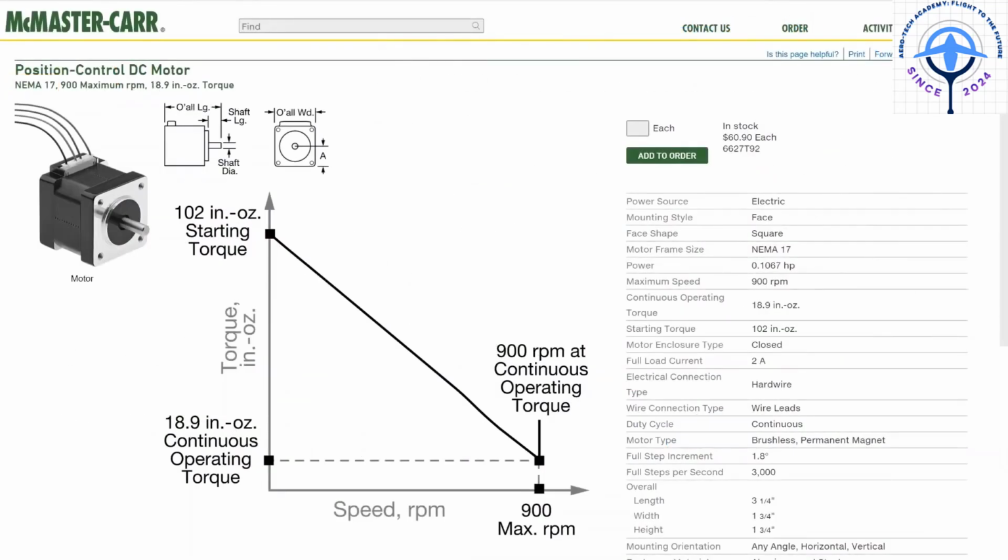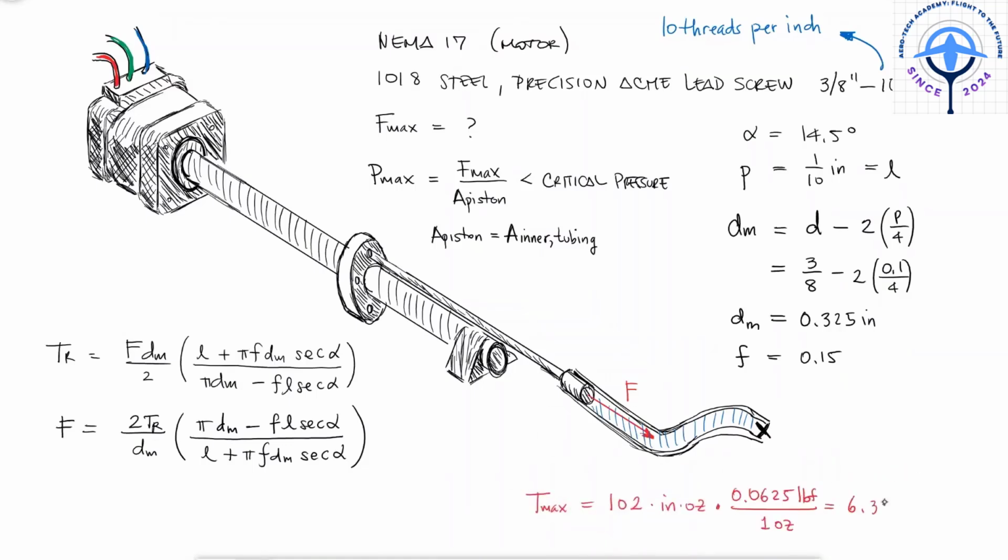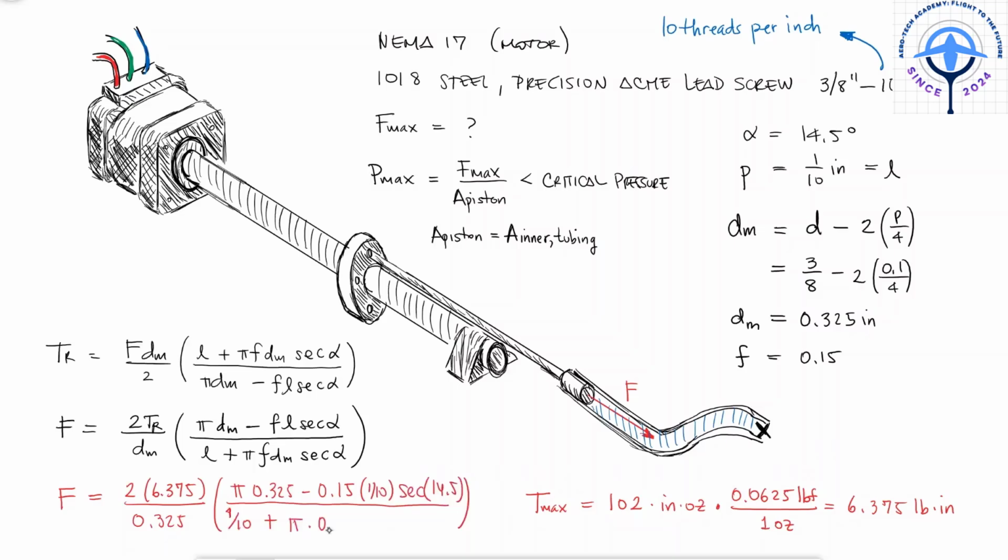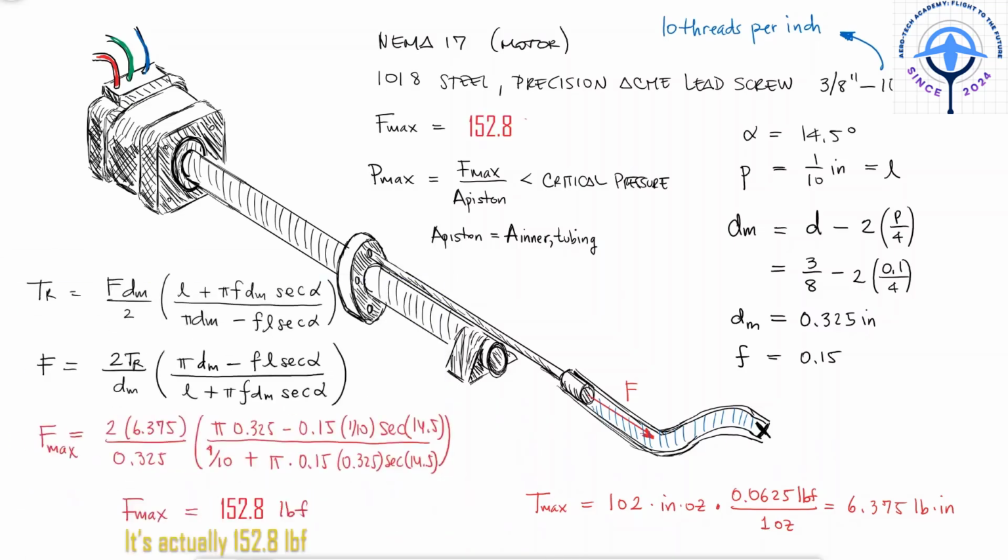When something gets stuck down the hydraulics line and the screw is not able to rotate, meaning its speed is equal to 0, the maximum torque that the stepper motor can generate is what is known as the stall torque. With a little bit of unit conversion, and knowing that every other unit is in inches and I probably want the force in pounds, we find that the maximum possible generated force is equal to 156 pounds.